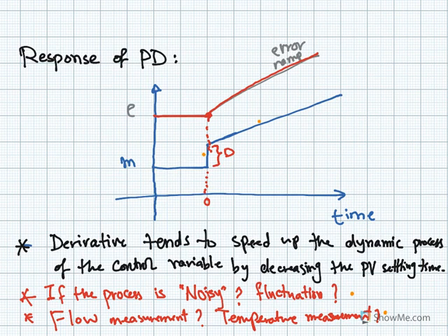After that, we can see in this part that the output is P plus D, which is the change due to the proportional and derivative modes. It is changing linearly with time, mainly due to the proportional controller mode.